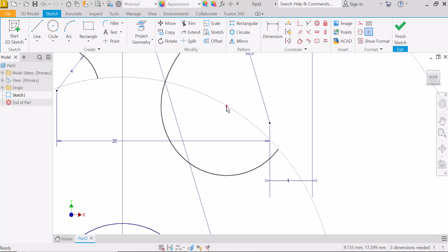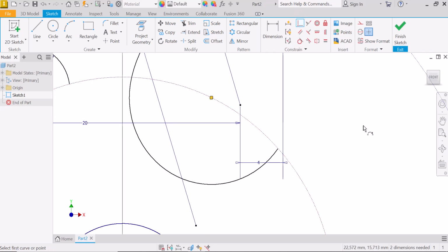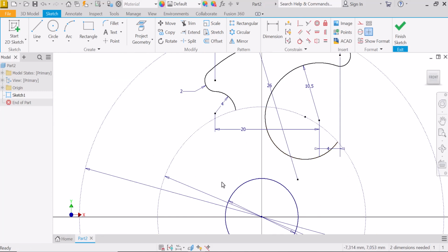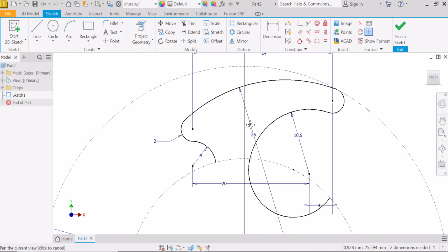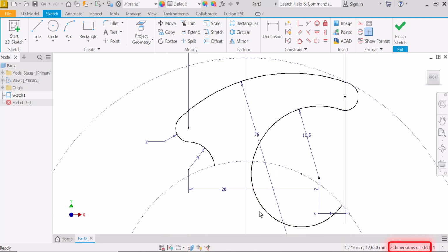Move this point slightly upward. Click on the Coincident constraint. Select the point, then select the 40 mm helper circle. The circle is now fixed. Press the ESC key. Using the light bulb icon, we can check how the sketch still moves. Here, it should be written, fully constrained.